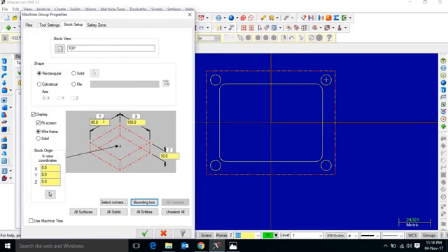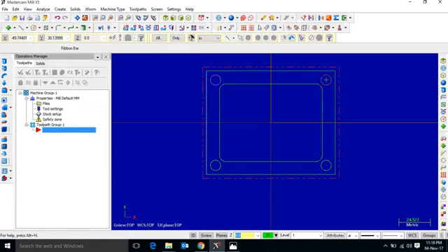Okay, we have to do a contouring operation also. So while selecting the raw material, we have to take some extra material on all the sides. So instead of 80 mm in width take 86 mm, right? So 3 mm on both sides. This is the extra one. So instead of 100 we take 106. And instead of 10 mm we select 11 mm. Okay, so there is 3 mm extra on all the sides.